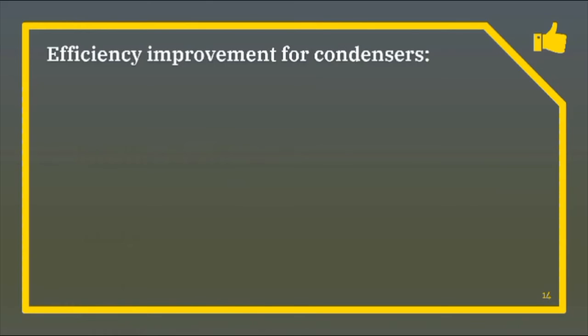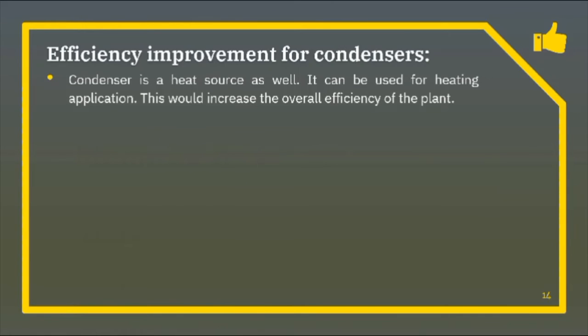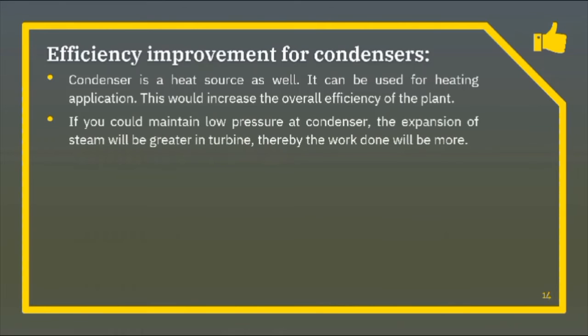Efficiency improvement for condensers. Condenser is a heat source as well. It can be used for heating application. This would increase the overall efficiency of the plant. If you could maintain low pressure at condenser, the expansion of steam will be greater in turbine.